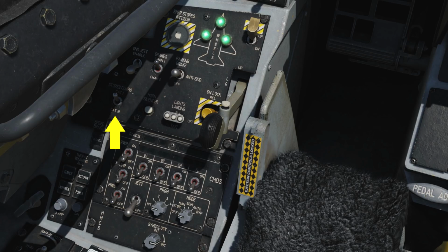When set to Cat 3, the flight control system limits the angle of attack and onset rates to increase the departure resistance. The landing gear horn silence button allows you to turn off the audio horn when you get below 190 knots, below 10,000 feet, flaps are extended, and the landing gear is not down and locked. Now this generally warns you to lower the landing gear, but you may also hear it if you get really slow in a dogfight below 10,000 feet.